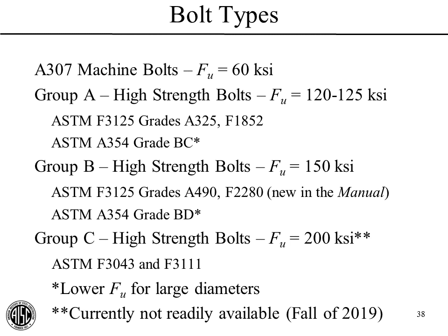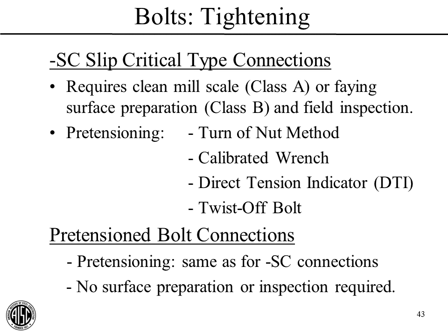All right. Question about bolt tightening. This question asker states, I understand RCSC discourages torque charts in determining acceptable bolt tightening requirements and specifies the methodologies you describe herein. Can you briefly explain why this is so? Well, the relationship between torque and the axial load in the bolt is highly dependent on the friction in the threads.